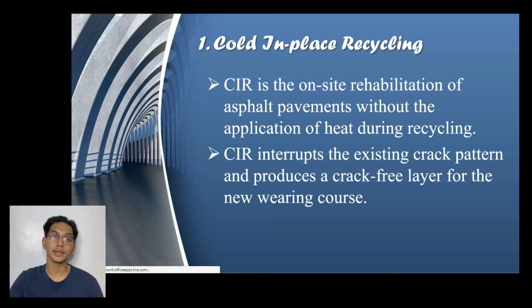One way of recycling in pavement rehabilitation is called cold in-place recycling. It is the on-site rehabilitation of asphalt pavements without the application of heat during the recycling. It interrupts the existing crack pattern and produces a crack-free layer for the new wearing courses.